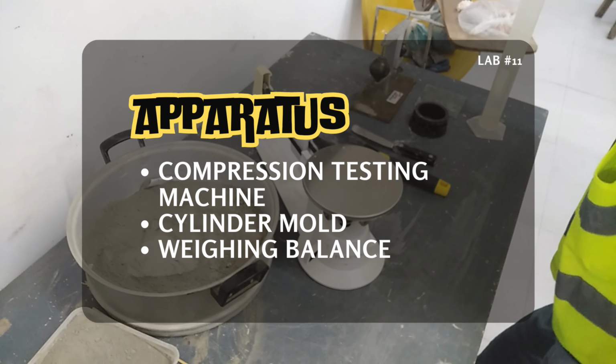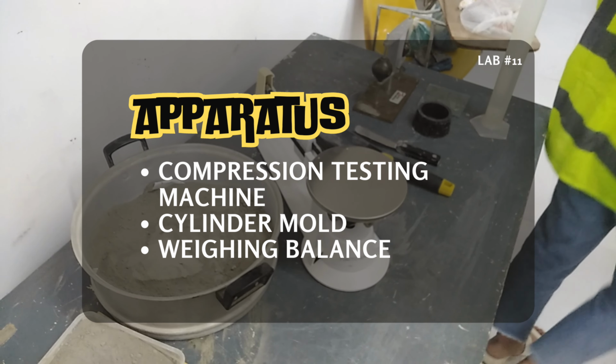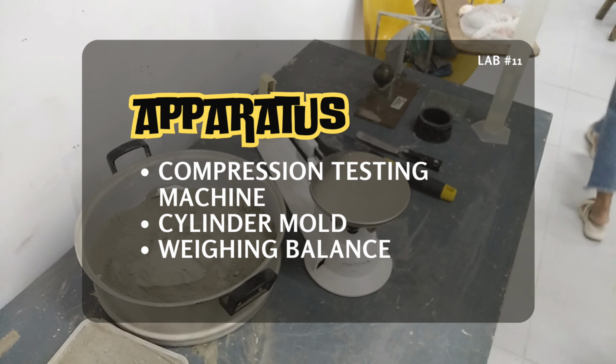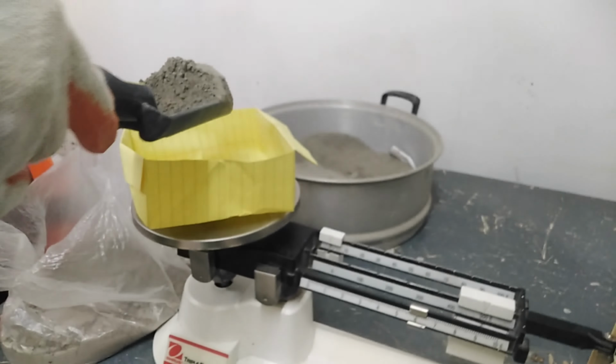For the apparatus, we're going to be needing the weighing device, Gilmore apparatus, trowel, molder, mixer, bowl, paddle and scraper, and lastly, glass graduates. First, prepare a batch of paste by mixing a certain amount of cement with the percentage of mixing water required for normal consistency as described in ASTM C187.